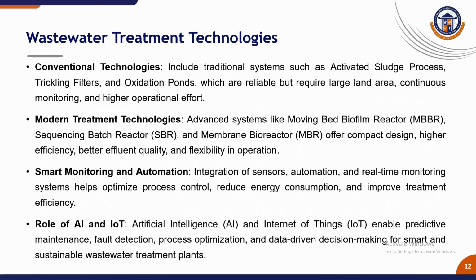Wastewater treatment technologies can be classified as conventional and modern. Conventional systems like ASP and oxidation ponds are reliable but require large land area and continuous monitoring. Modern technologies such as MBBR, SBR, and MBR offer compact design, high efficiency, and better effluent quality. With the integration of automation, sensors, artificial intelligence, and IoT, treatment plants are becoming smarter, enabling real time monitoring, predictive maintenance, and optimized performance.